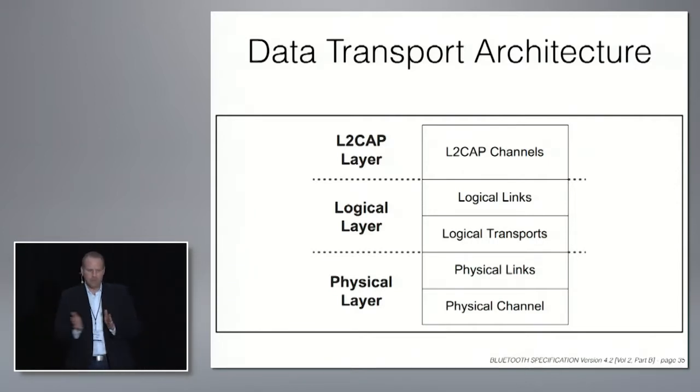So what do I mean by that? Minimally, when two devices connect to each other, there's going to be 4 channels. One channel is going to be for your basic frequency hopping. A second channel is going to be for adaptive frequency hopping, if the device supports that. A third channel is going to be your inquiry channel, and inquiry is going out and checking for discoverable devices. And a fourth channel for what's called paging, which is how devices actually set up their connections.